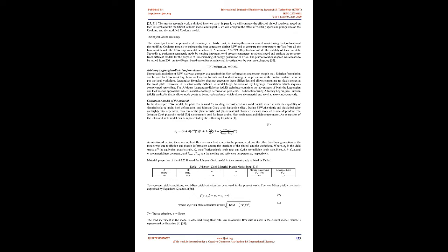Schmidt et al. 15 used a contact state variable, which represents slip rate between the tool and the workpiece, when equals 0, full sliding, equals 1, full sticking, and between 0 and 1, partial sliding/sticking. A 3D CFD model was developed by Nandan et al. 16, which considered partial sticking condition at tool shoulder and full sticking condition at the pintool interface.